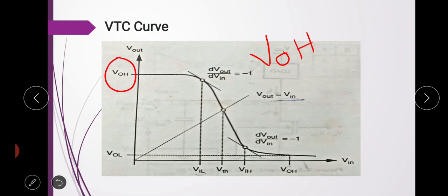In this case, the driver NMOS transistor is in cutoff and hence does not conduct any current. As we know, this is an enhancement type NMOS transistor, and to turn on an enhancement type NMOS transistor, we need a positive voltage that we denote as the threshold voltage. Below the threshold voltage, it is always off and no current flows through it.